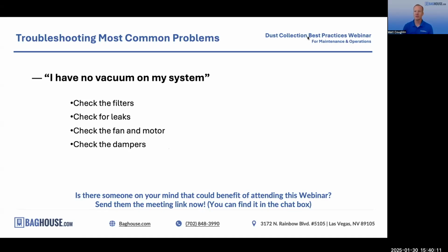So that's number two, fairly common. Usually that's not the sole problem, unless you are talking about removing entire branches and leaving branches open to atmosphere, which we do sometimes see, so you want to minimize those leaks in your system. Go walk your ductwork, figure out where you may have air leaking, and fix it.